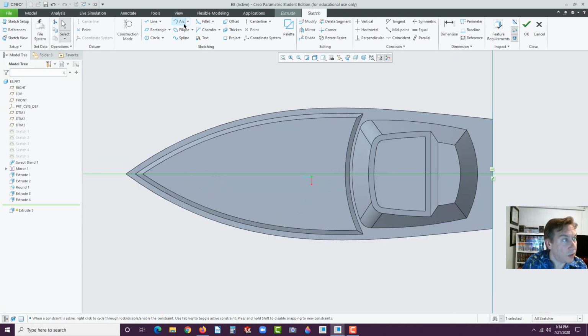And I'm going to use the spline tool right off of here, have it follow the edge, and then it's going to go in and then connect to that point. Middle click. Let's do another one, a little thicker this time. Try and get the same amount of points. Click right there, middle click.